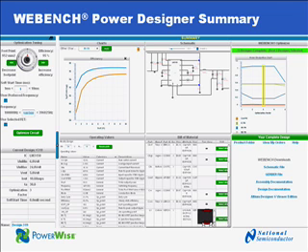Next one to the right is the schematic. Here you see what external components have been selected and the components that are needed. Then in the optimizer on the right-hand side, you see curves that show you the various stages that you can select from 1 to 5 with the top left optimization dial that lets you choose between size and efficiency. Left hand on the low side, you see your input data. In this case, 6 volts to 24 volt input range, 5 volt 10 amps output.